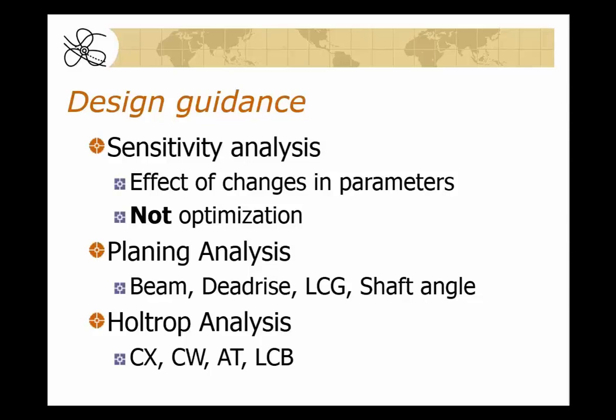Anybody who knows me knows that I have a particular problem with the concept of design optimization, not in theory, but in how it's frequently implemented. Optimizations can be very flat curves. So what we do with this is we give you the sensitivity in the planing analysis of what a change in beam, change in dead rise, LCG, or shaft angle might be. We also give you a ranking as to how important each change will be.